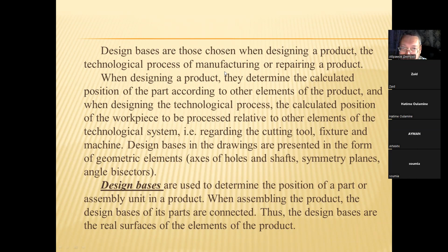When designing a product, they determine the calculated position of the part relative to other elements of the product. And when designing the technological process, the calculated position of the workpiece to be processed relative to other elements of the technological system, regarding the cutting tool, fixture, and machine.